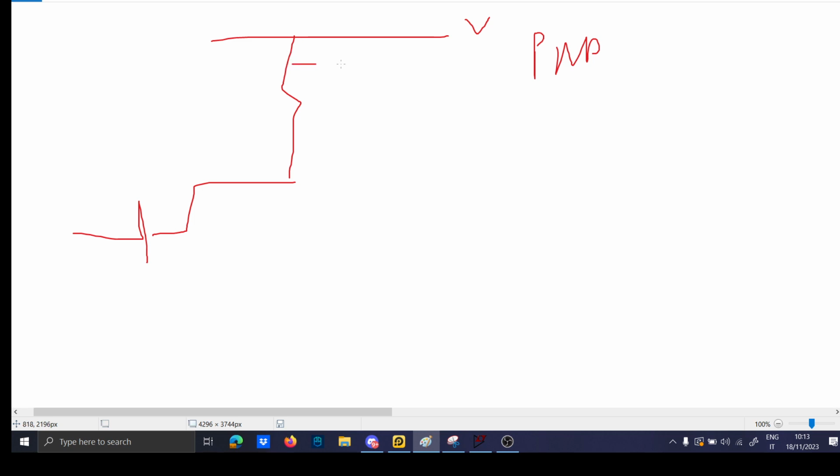Basically, there are at least 100 circuits which do the current protection. Now we have the output stage of a Schmitt trigger like this, and here there is the voltage. So the best way in this scenario is to implement a PNP current protection high side. The basic way to do this is just to connect the emitter here in this way, and the trick is to put a resistor here.